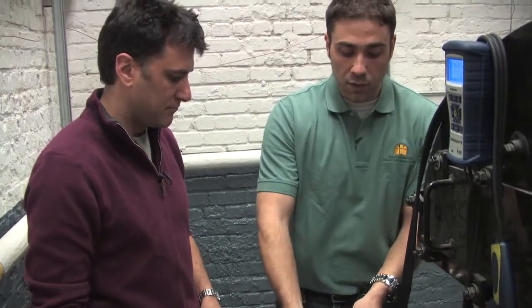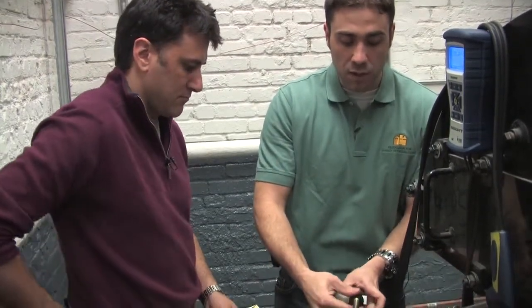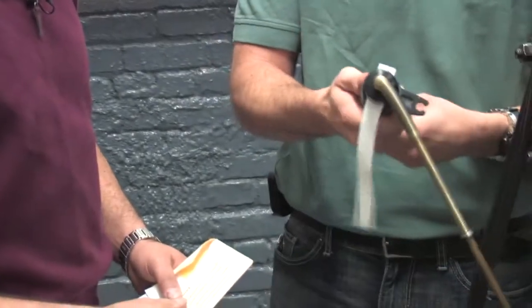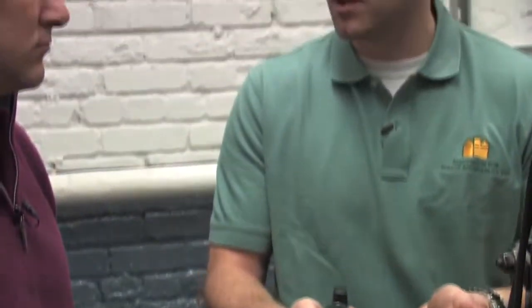Now, one thing when you do this test, what you need to make sure of is that all this equipment comes up to temperature. Because a lot of times, if this is out in the truck or the van or whatever you're using, and it's cold on a cold day and you bring it in and just start to do the test, you're going to get condensation inside here. Because you're going to be pulling hot flue gases into a cold metal pump, and they're going to condense and turn to water. Then this filter paper is going to be covered in water and it's not going to give you a good reading.